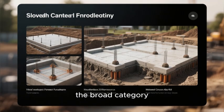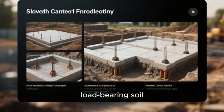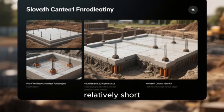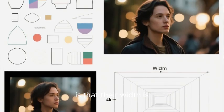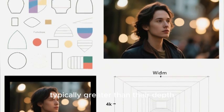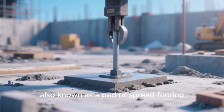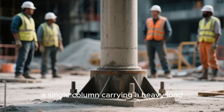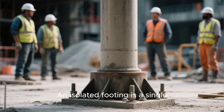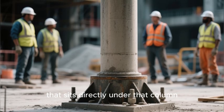Let's begin with the broad category of shallow foundations, used when stable, load-bearing soil is found within a relatively short depth below the ground surface. Their key characteristic is that their width is typically greater than their depth. The most basic type is the isolated footing, also known as a pad or spread footing. Imagine a single column carrying a heavy load. An isolated footing is a single, wide block of concrete, often square, that sits directly under that column.